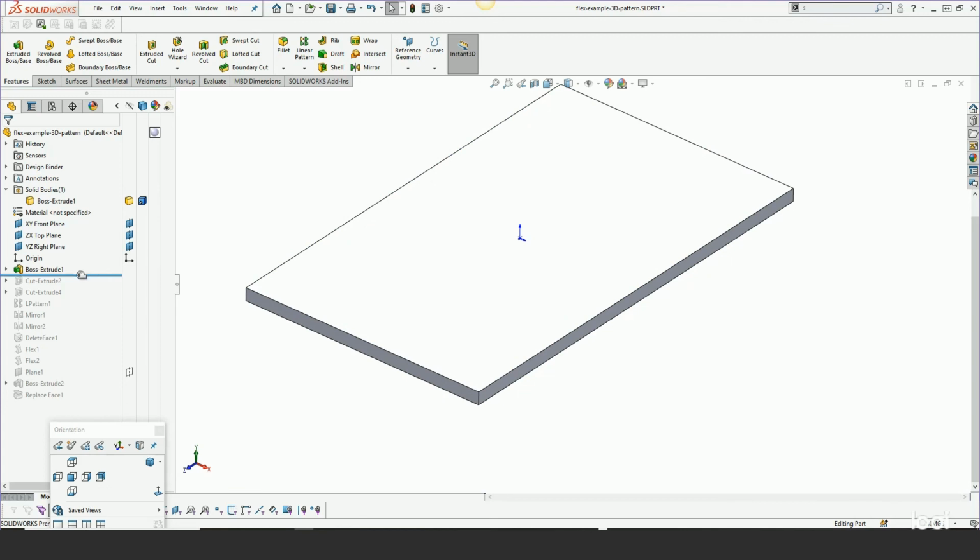With that block, we do a cut. And then we do another cut, which uses Derive Sketch. If you never use Derive Sketch, it's super useful for this kind of thing. Basically, I want this one pattern seed to drive this one that I have set up diagonally here. And so any changes I make here will change to the derived pattern. And then I create my pattern.